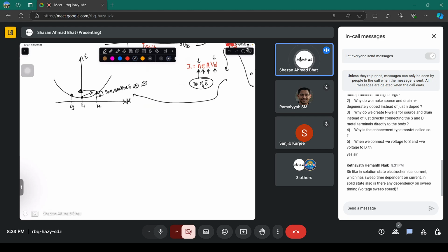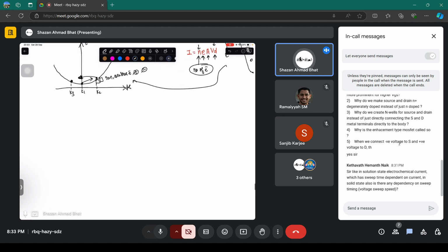So that gives rise to basically the resistance. Why? Because in real space the electron was moving in this direction, but now because of scattering it's moving like this. It's scattered again, moving like this, and then this, then it moves here. And these particular events basically give rise to the resistance inside the material. That's why you don't have a pure channel without any resistance.